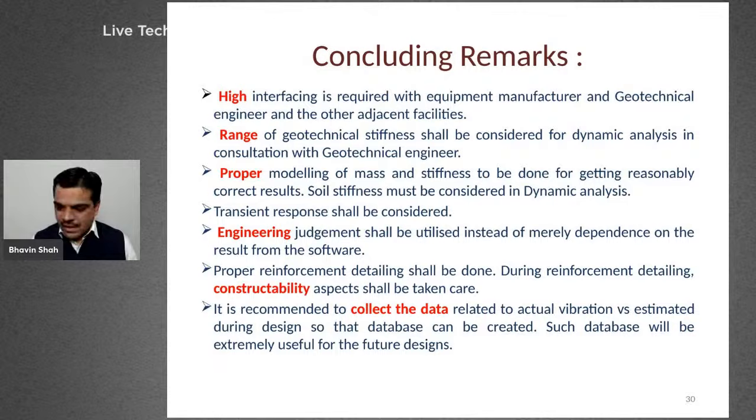We should always ensure the foundation has at least an air gap, or proper sand filling, so that a proper gap is ensured with adjacent foundations and the vibration from this tabletop foundation shall not transfer to the other adjoining foundations.